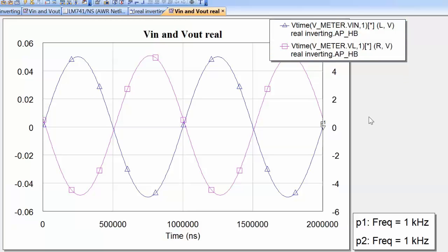And you can see that we have a similar situation as we did before. There is, however, a little difference, and we'll see this in a moment. Press Ctrl M and put your marker on one of the voltages, and then press Ctrl M again and put the marker on the other voltage waveform. Then right-click on each marker and select Marker to Max. And you can see that in this case, what you seem to have is a greater voltage gain than you had previously. Don't be fooled, because actually what's happening here is that you have an offset.